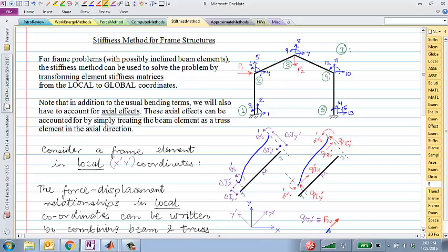So for the truss problems and for the beam problems, it was 2i minus 1 and 2i. And maybe the easiest way to remember that is you just take the number of degrees of freedom per node. So for these problems, there are 3 degrees of freedom per node. If you have 5 nodes, then 5 times 3, total is 15 immediately, right? And so 3i would definitely be the 3rd degree of freedom associated with each node. The previous 2 would just be 3i minus 1 and 3i minus 2.